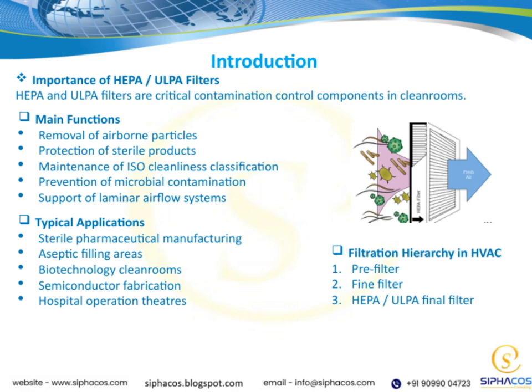Now, why are HEPA and ULPA filters so important? They play a critical role in contamination control within cleanrooms. Their main functions include removing airborne particles that could compromise product integrity or process safety, protecting sterile products from microbial contamination, and maintaining the ISO cleanliness classifications necessary for many high-precision environments. They also support laminar airflow systems, which help ensure a uniform and contaminant-free airflow pattern.